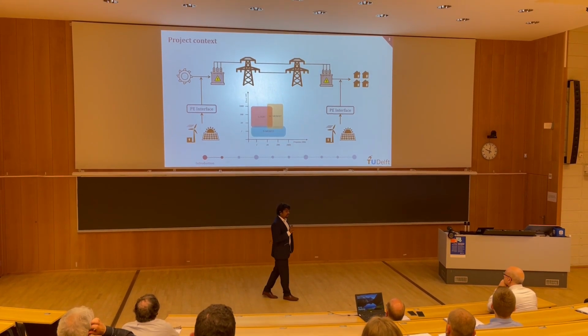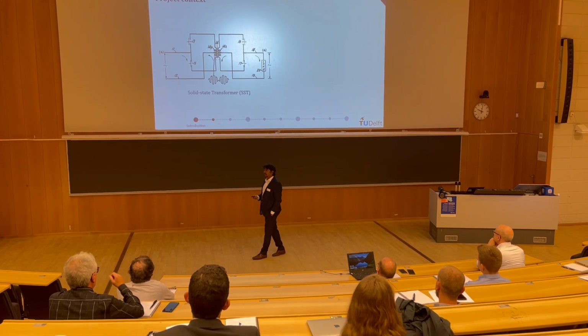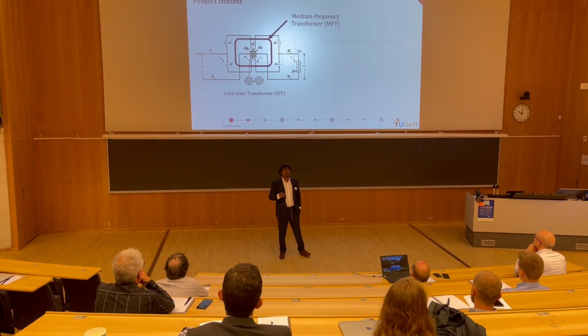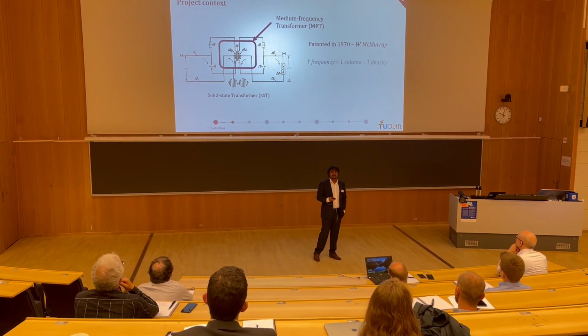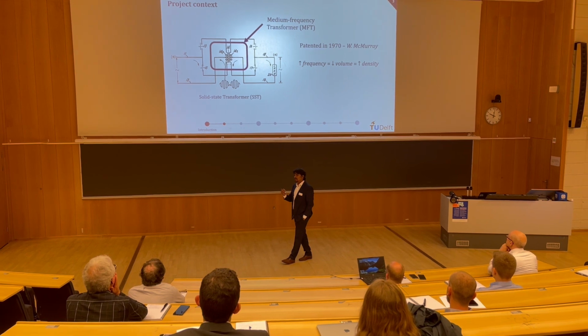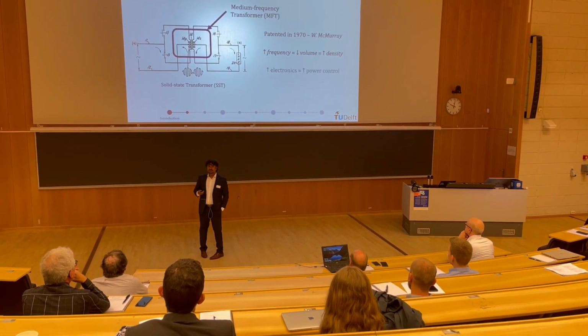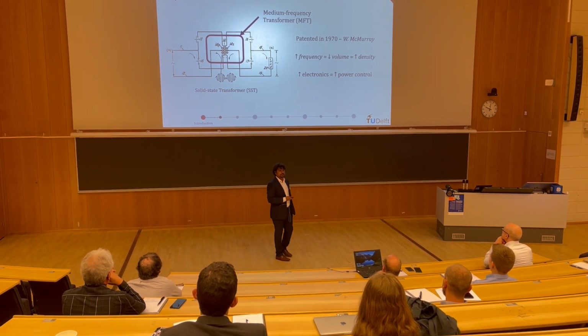One important powertronic interface is the solid-state transformer. Now, the solid-state transformer has a medium frequency transformer. It was patented back in 1970. The idea is that the higher frequency allows smaller volumes and therefore higher energy densities. Also, the increasing amount of powertronics gives us more control over power flow.